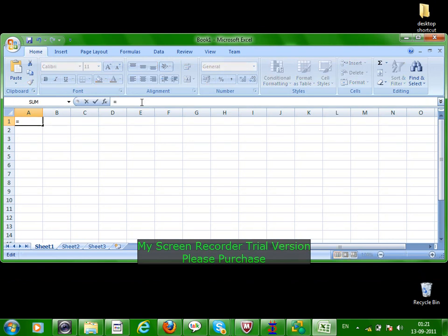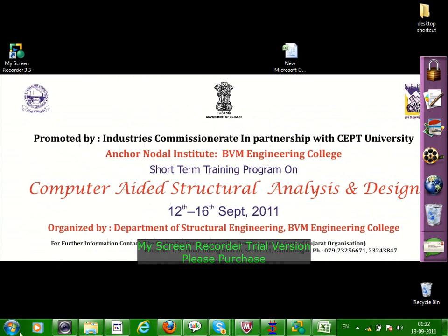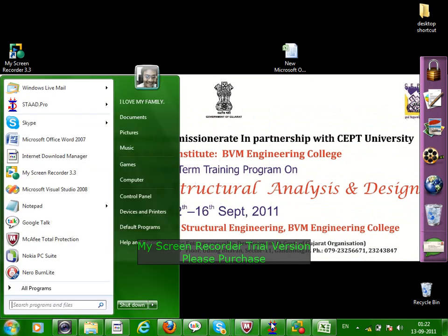Now the height of the story at the first level is 3.2 with the masonry density 20 kilonewton per meter cube, with the thickness of the beam at this level 300. So 0.3 and a story height of 3.2 meter. So this is 19.2 kilonewton per meter run, that is your load. So that is your member load you have to give at the external periphery at each level.